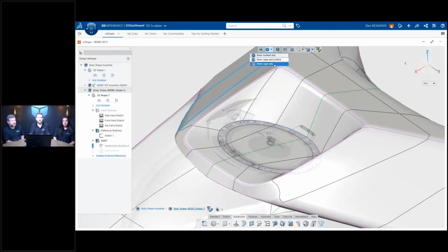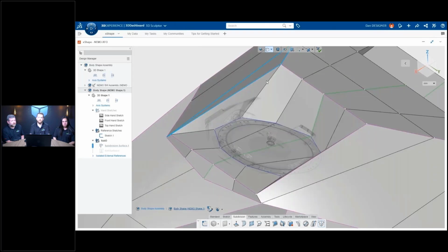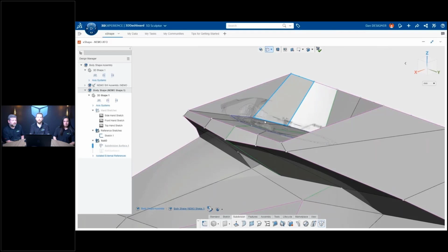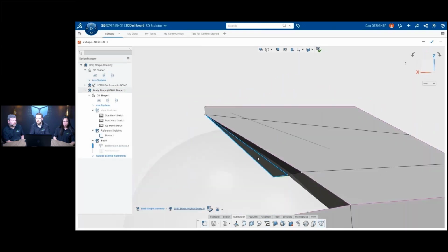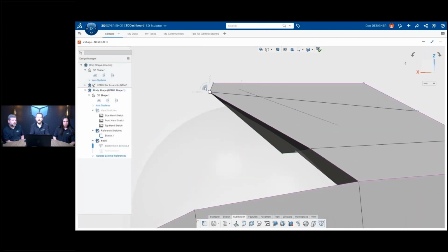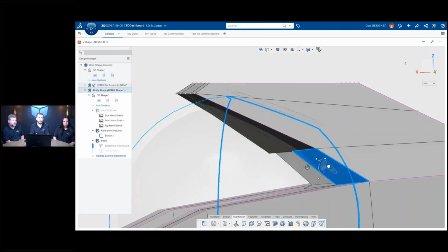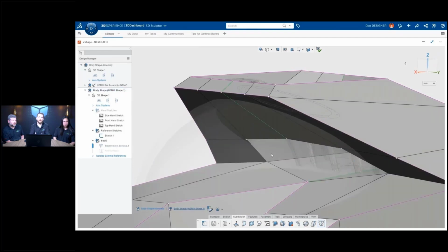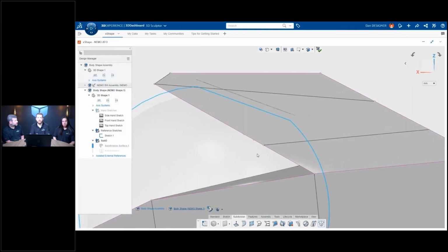So if we display our Cage View only, we can see that the front vertices in our model are a little bit off. Well, we can select those vertices in sequence, and then those can be aligned together, creating just a nice uniform geometry. Viewing our model from the side, we can see that not only our vertices, but our faces are just out of alignment a little bit. We can select those faces, and we get the ability to add a coincident relationship, just like adding mates in an assembly, getting a nice, smooth, clean surface in our model.